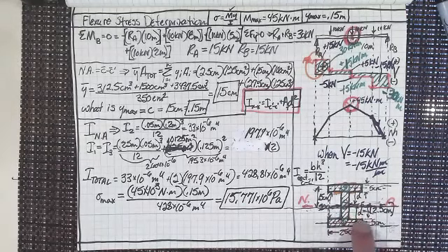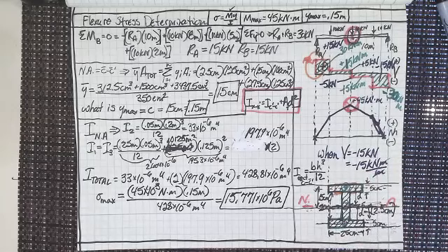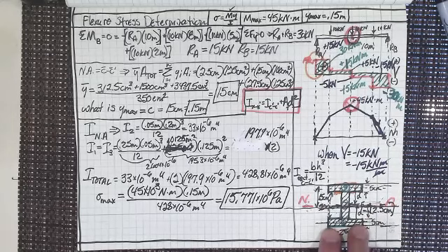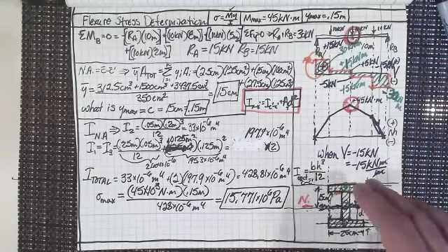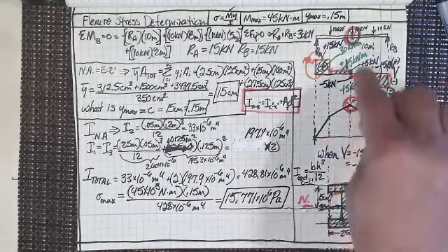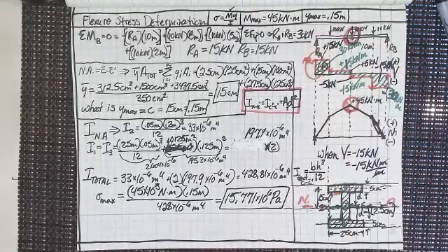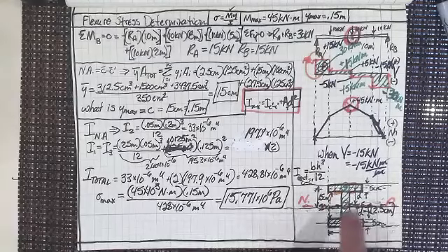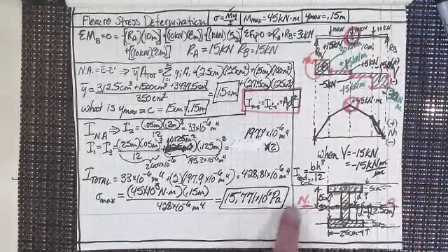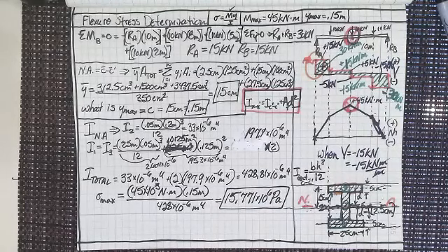Hey, couldn't I just nail this all together with 25 centimeters? That's like a 2 by 10, isn't it? And 5 centimeters, so I've got a 2 by 10, 2 by 10. I could even throw a 2 by 10, an 8 by 10 in there, and there you go. Then I could just use this to hold something up that's 30 meters long. That's right. If you've glued this together well and screwed it together, no problem. 15 megapascals, wood can just about take that, depending upon the kind of wood that you're using, of course.